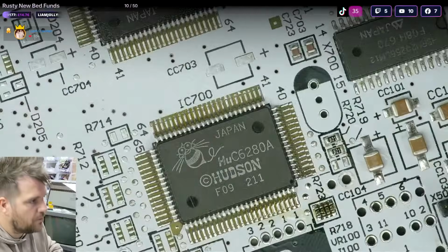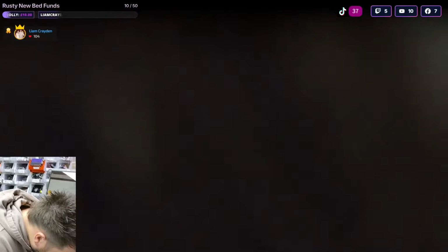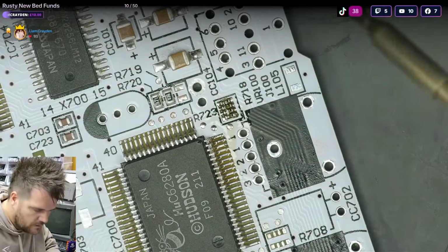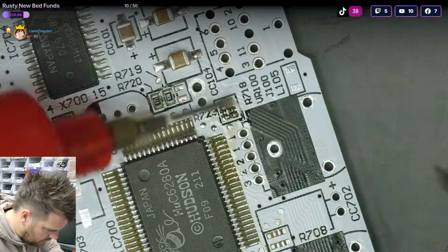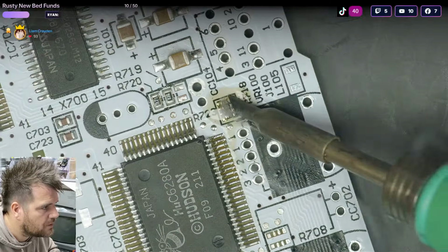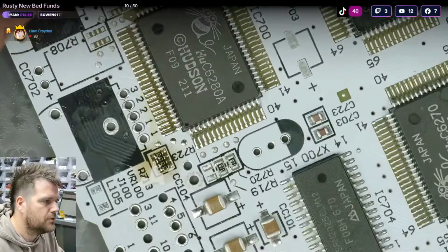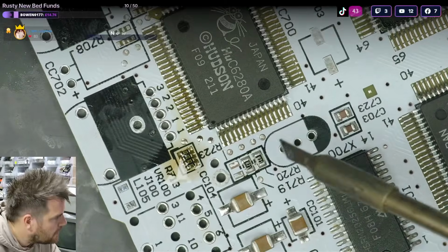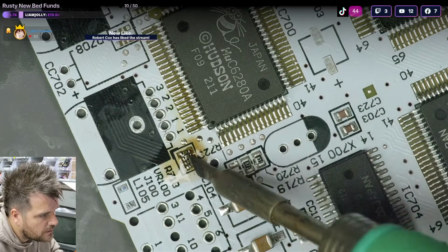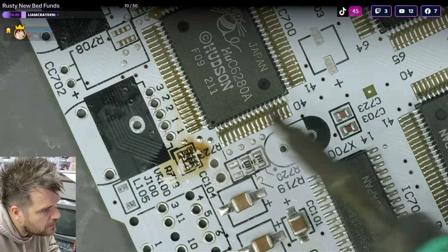I'll just tap up the corner resistor there. It's got barely any solder on. In fact, you could also clean the iron and just go down them, because they weren't well soldered on the original board, so they're not carrying much solder over to this board. So we'll just tack them up with the iron as well. Get a nice bead on there. That's it.